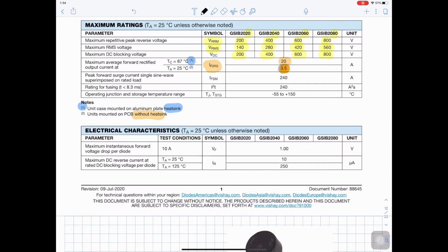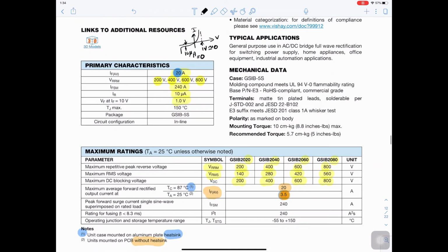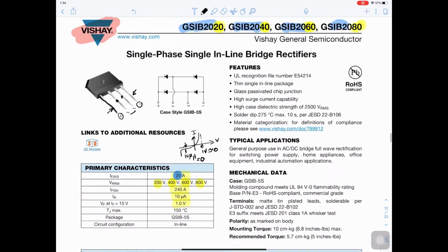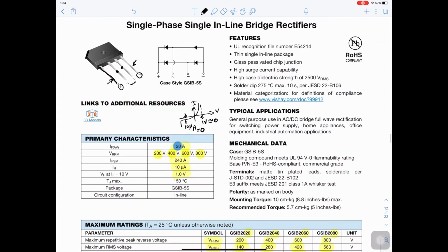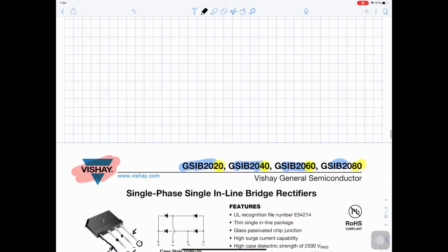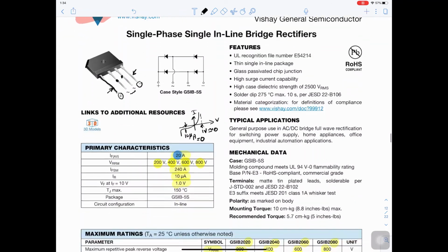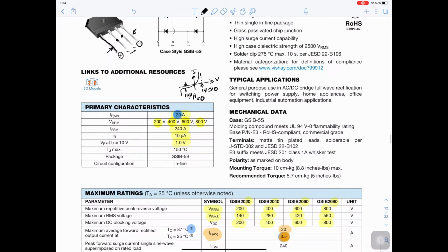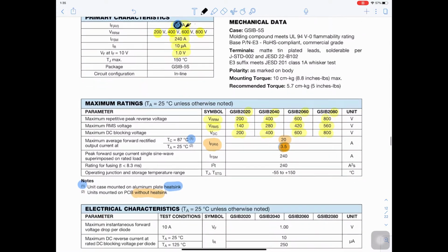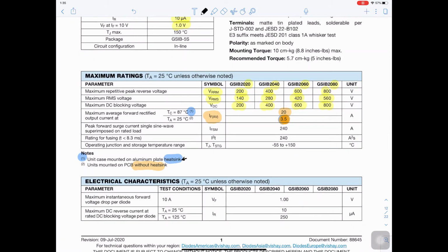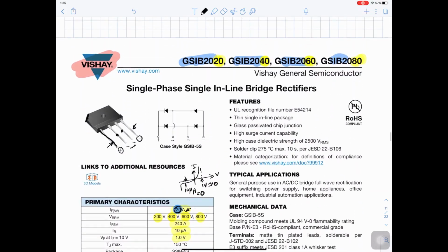So you are getting 1/8 of the value if you don't use a heatsink. So sometimes a heatsink can increase the rating, in this case multiplied by 8, just by using the heatsink. So pay attention to which values you are reading. The value here in this table is a rating, because the value is written as 20, but if you read through the details, this 20 is with heatsink. So you have to add an aluminum heatsink.